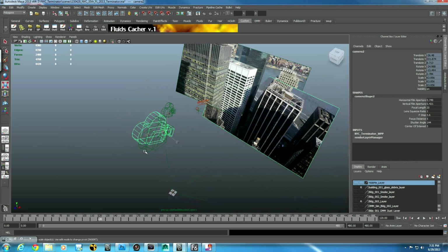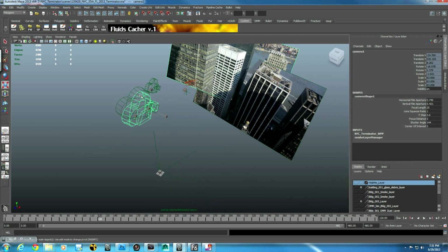So here is camera 1 and camera 2, and this is camera 1. So the way I did this is I created the camera, which by default goes to 0 0 0 in X, Y, and Z, and then I moved the camera manually in the Y direction to roughly around 330, and that was based on some calculation as to how high I must be from the ground level when I took the picture. I simply took the number of floors in the building where I was standing times, I don't know, 8 or 10 feet per floor, plus some margin of error and some space between the floors, and that put me roughly where I wanted to be in the 3D space.